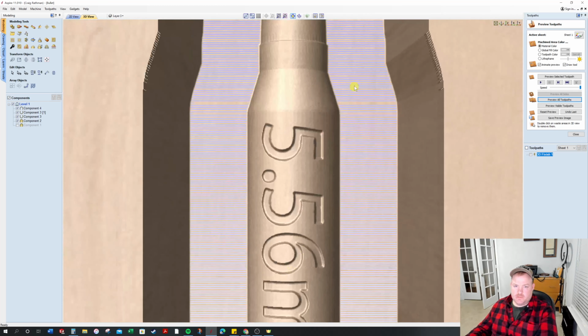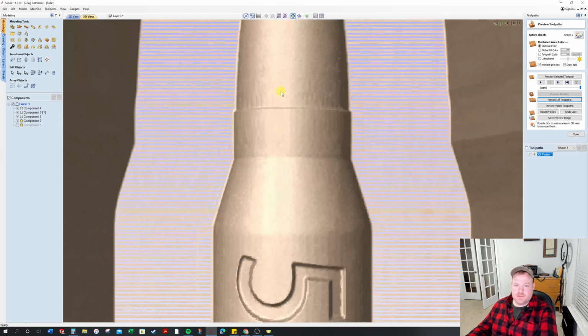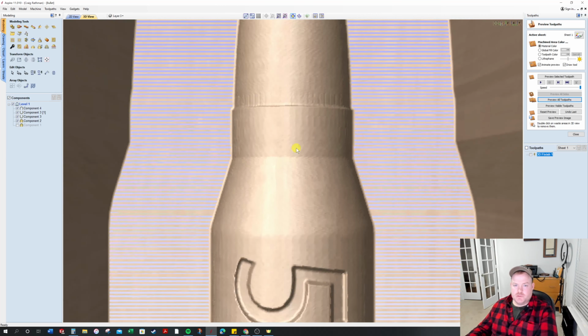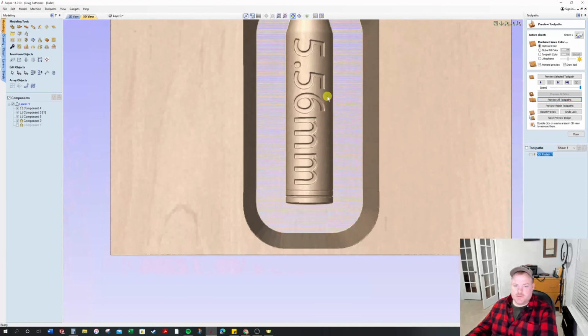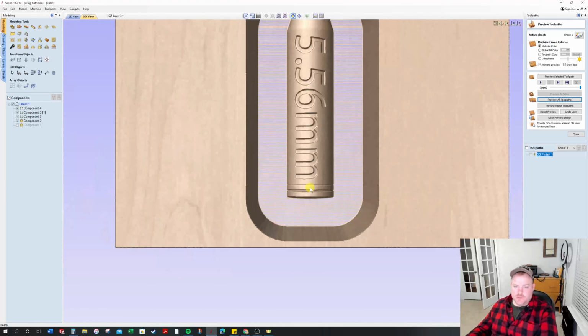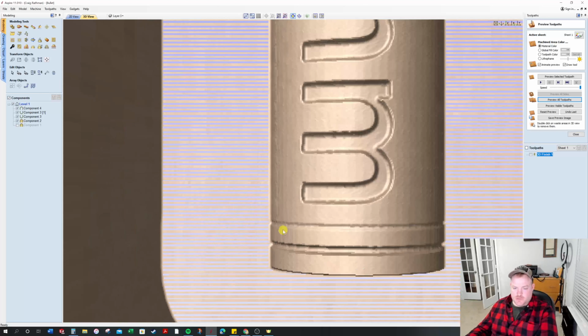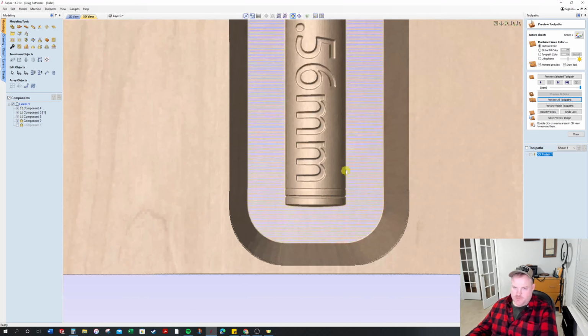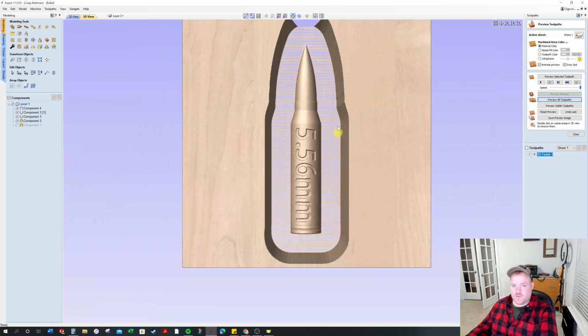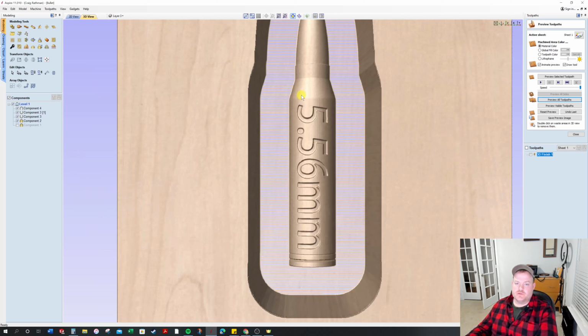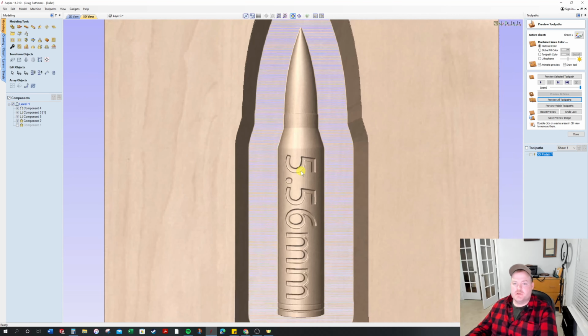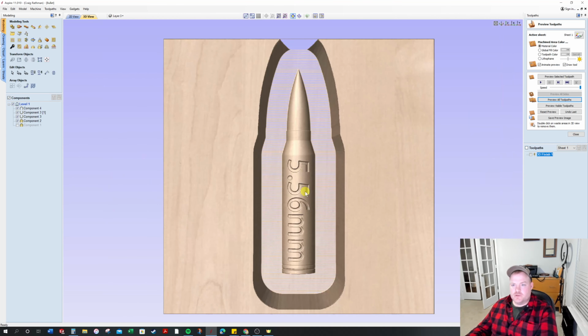I mean, you're basically doubling, or you are doubling the amount of lines that it has to calculate. So even now, you know, you're still barely seeing those ribs. I would definitely go in there and exaggerate them more. Maybe double the width and double the depth. See, it's showing up more here. You're getting a little bit of it here, but that's some things that you just have to do with models. If you're really wanting those features to show up, you have to exaggerate them. It's just the way it works.